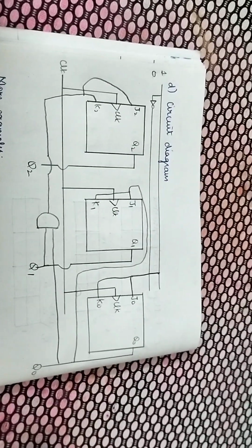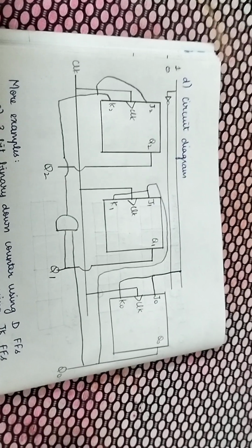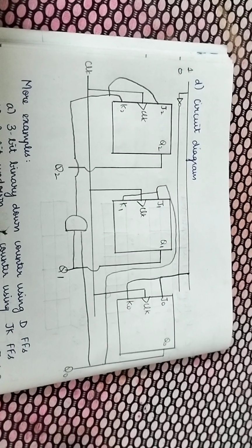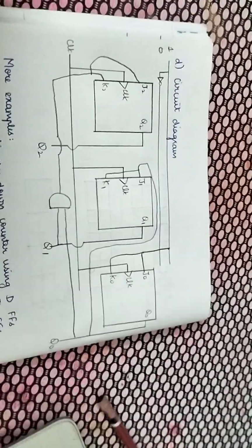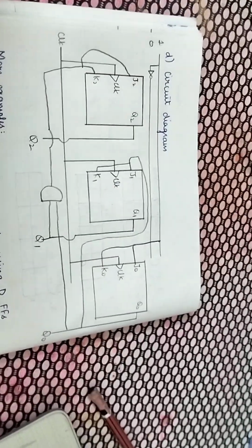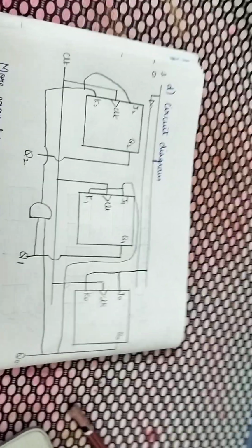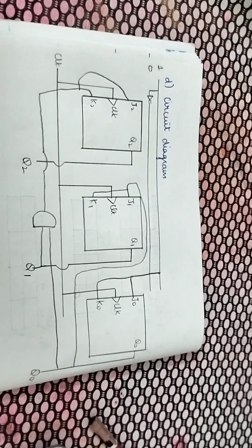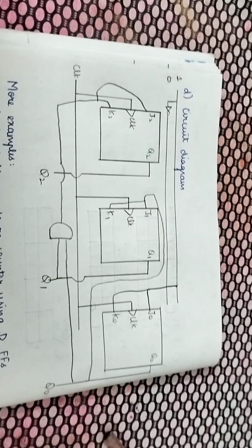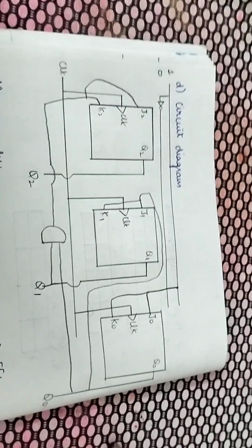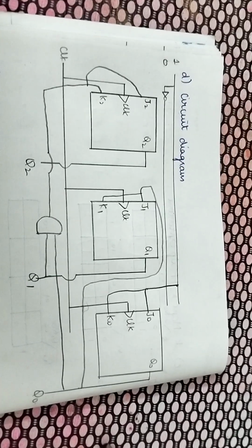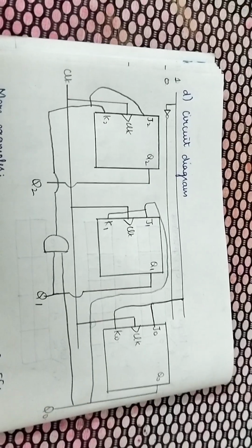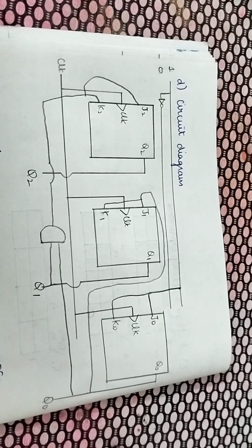So to quickly summarize, we drew the state diagram. We constructed the state table which has current state, next state and flip-flop inputs. We derived the flip-flop inputs using the excitation table. Then we drew Karnaugh maps and identified the expression for each input J1, K1, J0, K0, J2, K2. Then we connected the appropriate gates and terminals using a circuit diagram. So this is a 3-bit binary up counter. So when you connect 3 flip-flops in this fashion, it will count from 0, 0, 0 to 1, 1, 1 and again 0, 0, 0 and so on.